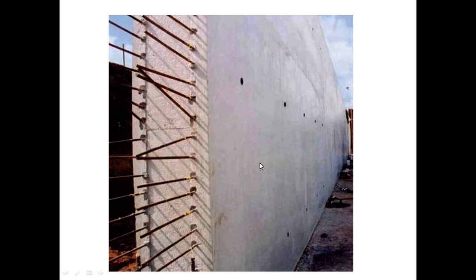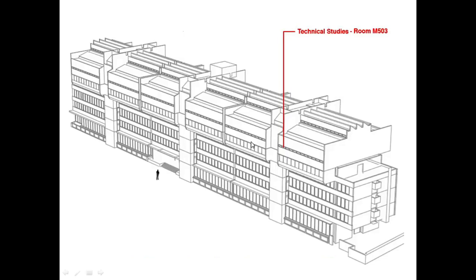Again, I'm not going to go into a lot of detail about concrete, but suffice to say that when you pour it, you have to get the air out of it. You pour it into a mold, and there's air when you're pouring concrete. To get the air out of it, concrete is actually vibrated to suck the air out. Self-compacting concrete sort of does that. There are certain chemical additives that do it all by itself, so you get this beautiful shiny finish.